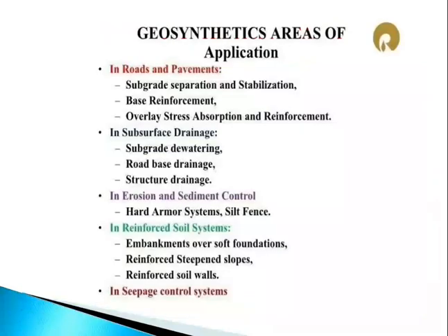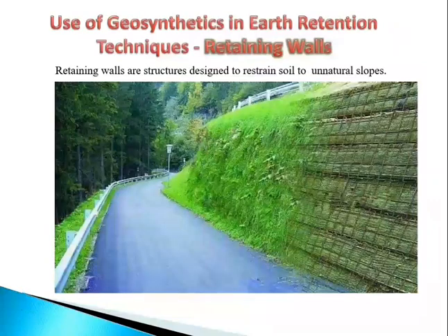Now the geosynthetics areas of application. In roads and pavements: subgrade separation and stabilization, base reinforcement, overlay stress absorption and reinforcement. In subsurface drainage: subgrade dewatering, road-base drainage, structural drainage. In erosion and sediment control: hard armor system, silt fences. In reinforced soil systems: embankments over soft foundation, reinforced steep slopes, reinforced soil walls, and in sewage control systems.